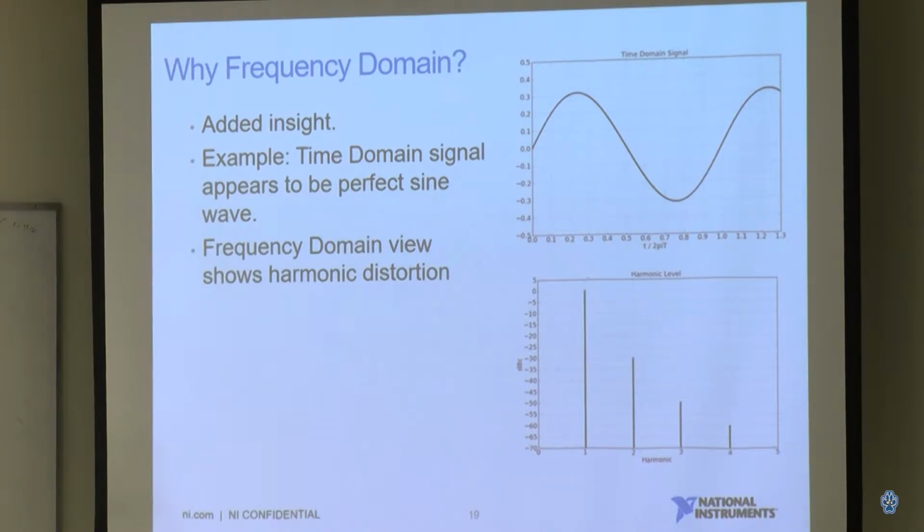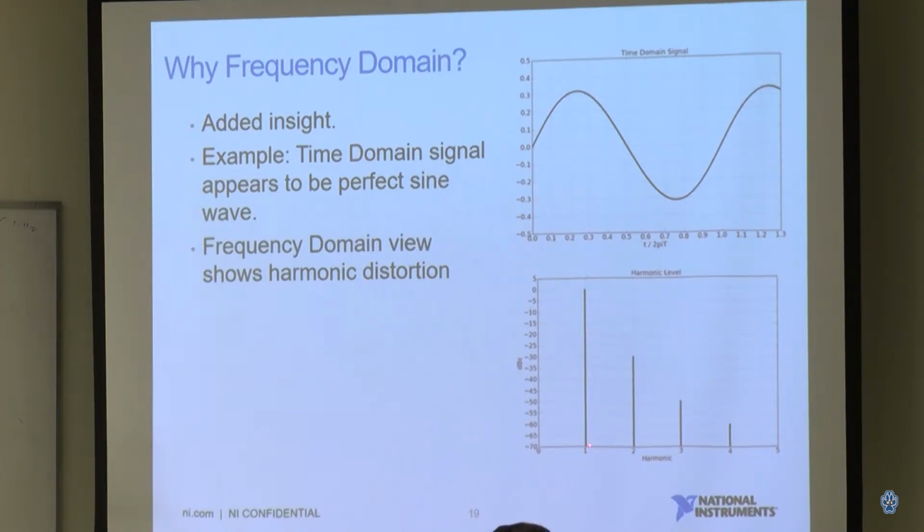So why do we talk about frequency domain? Why do we create a new definition, right? In RF, because in time domain it's a sinusoid signal, you don't really see a lot of information. All you see is the amplitude at different times. However, when you go to frequency domain, remember a perfect sinusoid signal will be a single tone at a particular frequency.